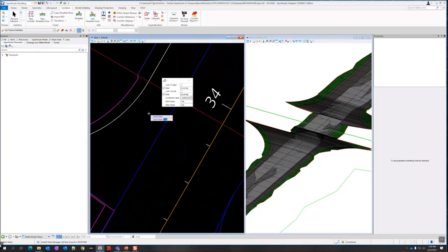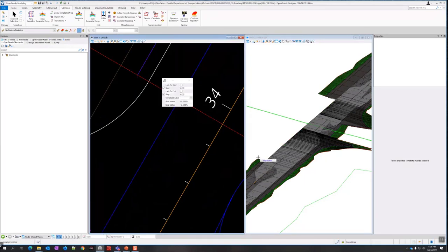Now the start and stop value. The switch in the template library is set up so that when you set it to 1, it toggles it on and off. So I'm just going to change that to 1, for both start and stop, and accept that. Now watch what happens over here in the 3D view as it reprocesses. So that whole section goes away.